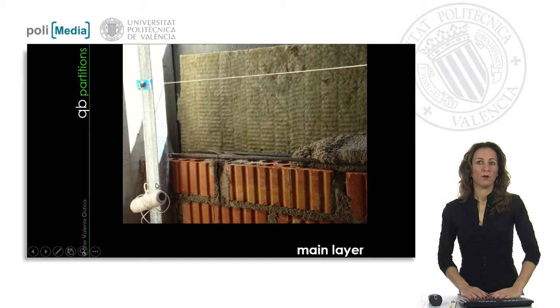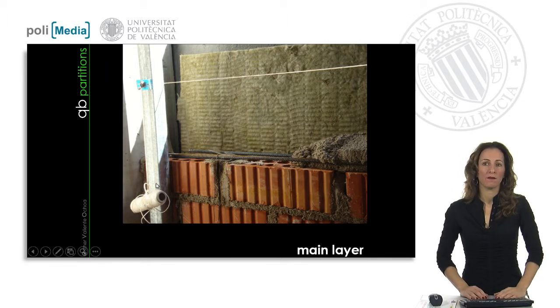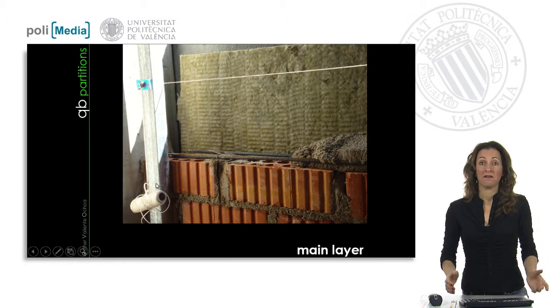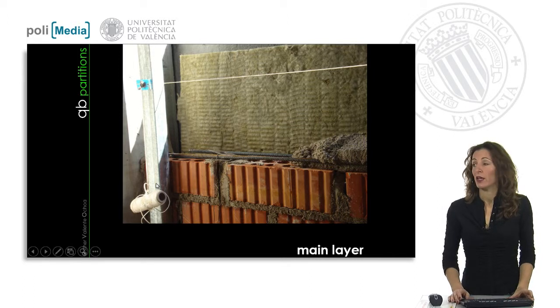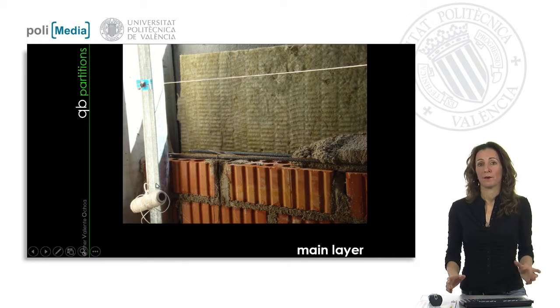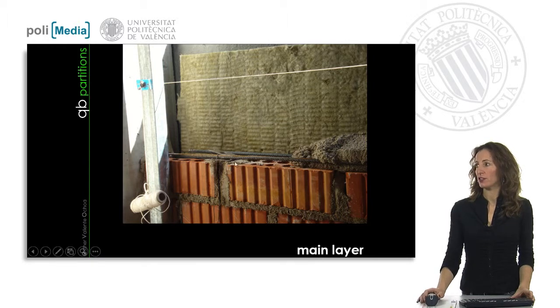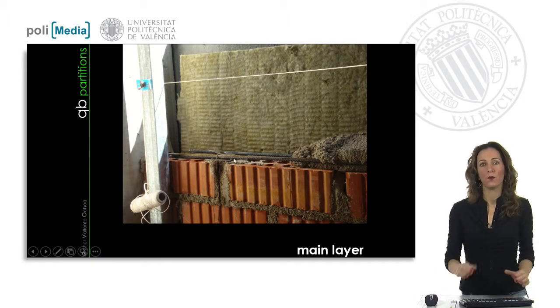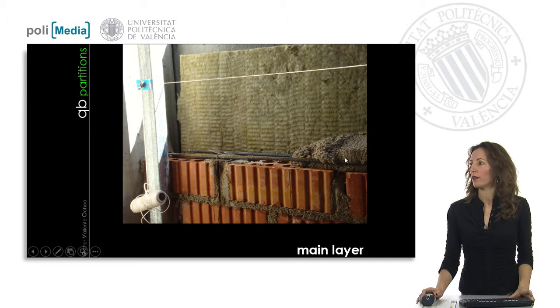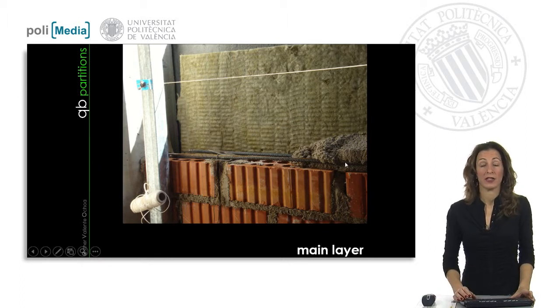If necessary, we have to reinforce our brick wall in some of these rows. Depending on the proportion between the width and the height of the wall, we will calculate how much reinforcement we need. In all cases, we should fit it into the middle of each row and cover it with all the cement mortar as much as we need.